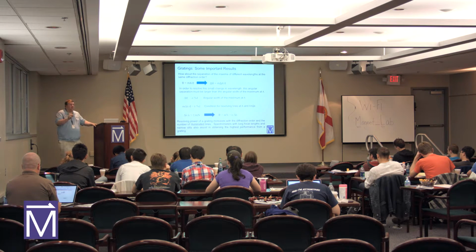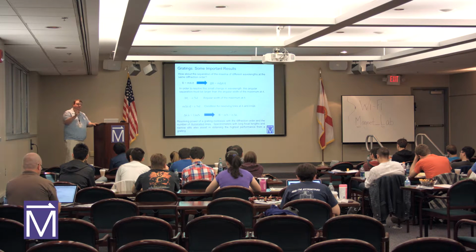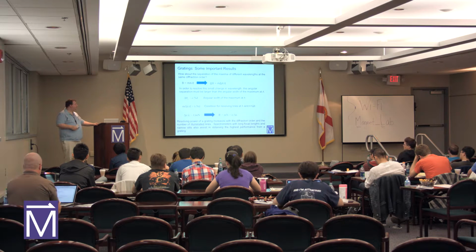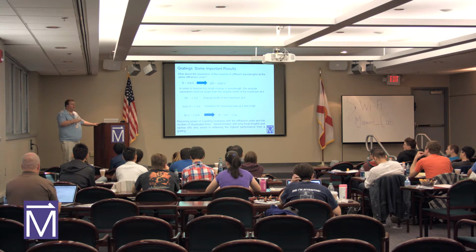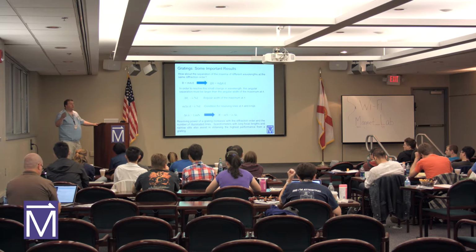Now, the other aspect of this is on the output slit. You don't have an output slit in the case of a CCD. So what also determines it on that side, since the output slit is important? Well, in a CCD, it's the size of an individual pixel, all right? So an individual pixel is what gives you your resolution in the detection. So you're looking for the smallest size pixel that you can get. And often I tell folks that you use in the calculation for the bandpass whichever is larger, the input slit or the size of the pixel.